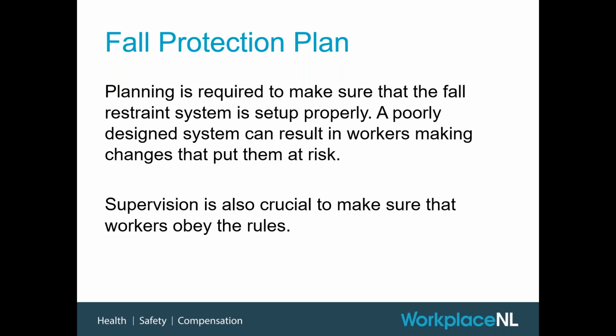So as I talked about a little bit earlier, this is really a system, the fall restraint system. That's what we're talking about here in this section. Wherever you have one of these systems, whether it's restraint or arrest, you do need to do some planning to make sure that the system in particular is set up correctly. A poorly designed system can result in workers making changes to the system because they want to be able to finish their work. And these changes could potentially put them at risk.